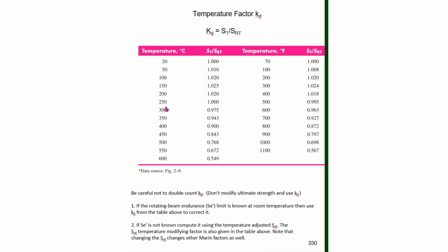You can see as the temperature continues to increase, we have quite a rapid drop-off in the Kd value. Now, we need to be careful not to double count Kd. You don't want to modify the ultimate strength due to temperature effects, and use Kd.